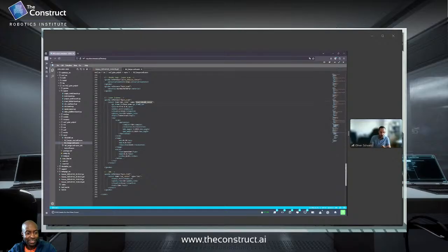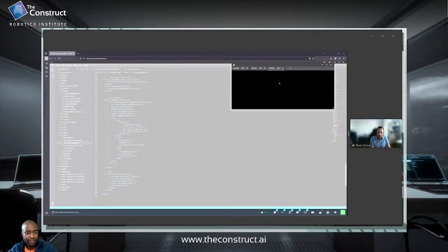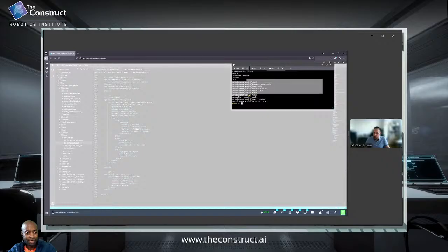While I was able to bridge the laser scan topic of Gazebo to the scan topic of ROS2, it wouldn't fit the frame, because it was not the base scan frame but this concatenated frame, a combination. I really struggled to find out what was going on because I checked the bridge, whether it was working, if I maybe had a problem there. I checked the Gazebo topic, which you can do easily, similar to the ROS2 part, where you can just echo the topics. You can also say gz topic -l for the list, and you get the list of the Gazebo topics. You can see the world, new world, which is basically my world, and then the laser scan. This is the one I wanted to communicate to ROS2 with my bridge.